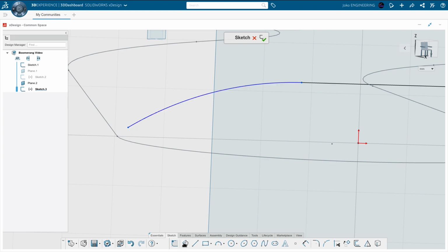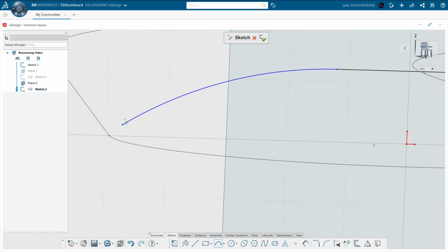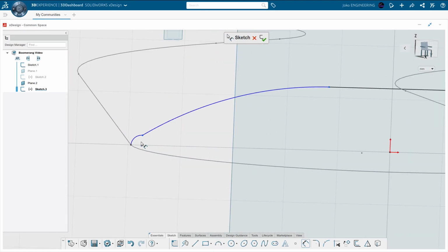Okay, I'm going to have to make a new arc that just has a tighter radius, or I'm scared I'm going to run into that problem again, right? So we're going to say dimension 2, tangent. Oh, again, that was a FreeCAD hotkey. I prefer to have T for tangent instead of, I don't know, 3-point slot.